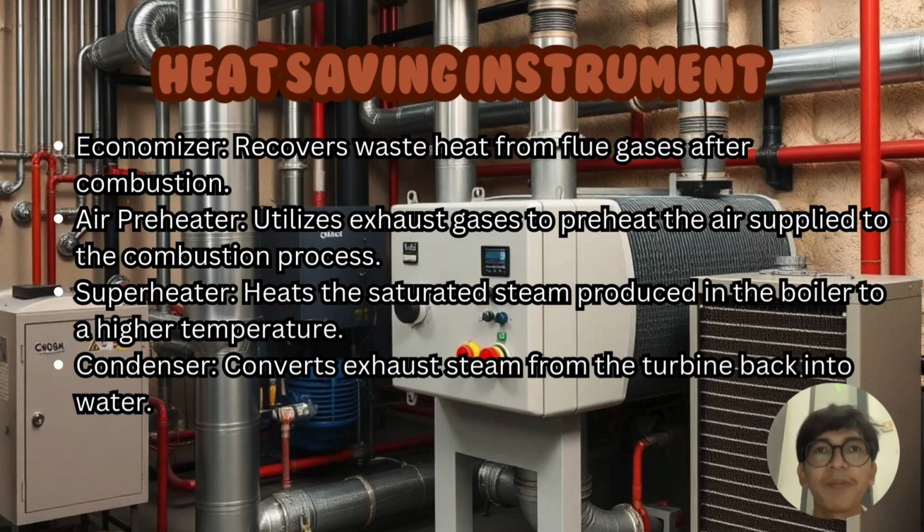And the third one is superheater. The purpose of superheater is heat the saturated steam produced in the boiler to a higher temperature. The contribution for the superheater is superheated steam improves the efficiency of the steam turbine by preventing condensation in the turbine and allowing the plant to operate at higher temperatures and pressures.